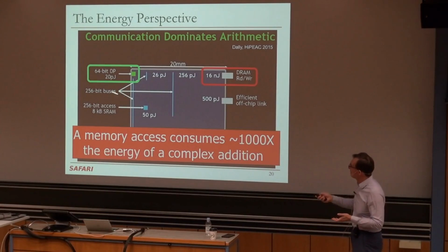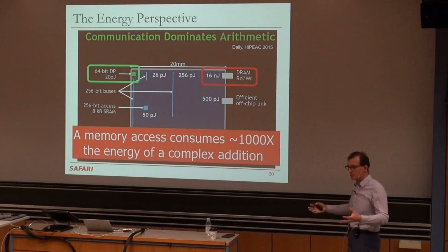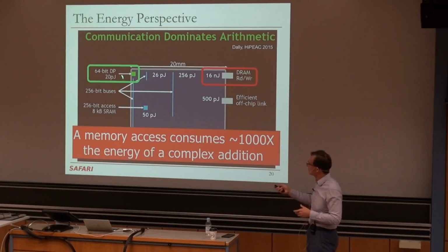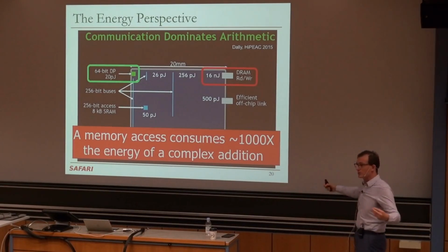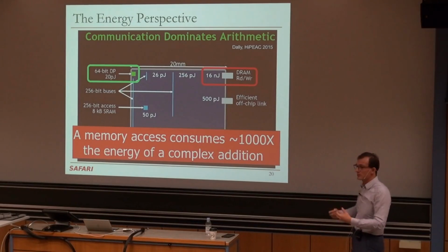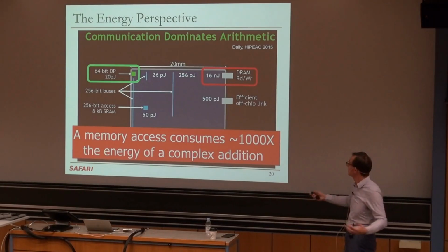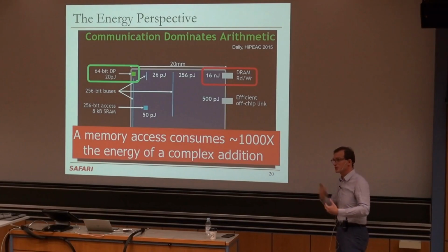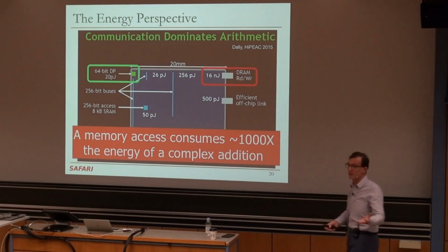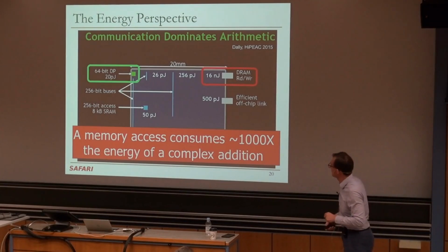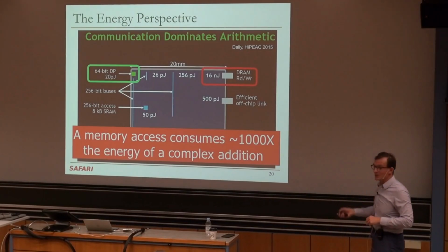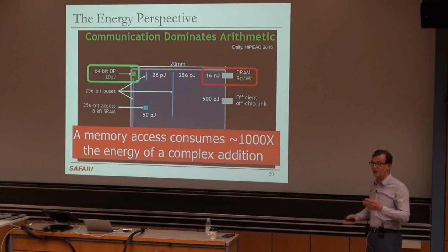So basically, this operation, double precision floating point, is actually complicated. It consumes very little energy because it's on chip, whereas when you're doing a memory access, you're exercising those huge interconnects, and they're consuming a lot of energy. And there's a lot of energy also consumed inside the DRAM chip, and there's also energy consumed because of the conversion going from on-chip to off-chip as well. As a result, you get this 100 to 1000x difference in terms of energy.